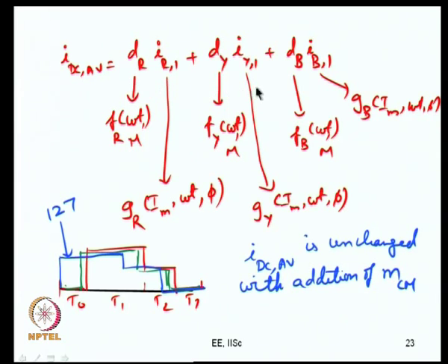So, this similar approach of DRIR etc., we will be using when we go to evaluation of switching losses or conduction losses. In conduction losses particularly, you will have 3 phase currents, and corresponding to every phase current there will also be some amount of voltage drop, and the average voltage drop in a device would once again depend on the duty ratio. So, you will see there is some similarity there. We will do that in one module later; the next module we will be doing the torque ripple analysis, and the module after that we will do this now, but this kind of analysis will also be helpful now.